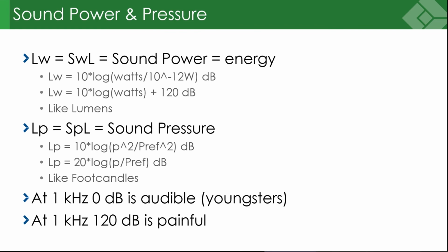So I also want our engineers to understand the difference between sound power and sound pressure, because that's really critical to specifying equipment. When you see something that says LW, the way I do that in my mind is I go, W is watts, that's power. And sound power is the amount of sound energy coming out of that piece of equipment.